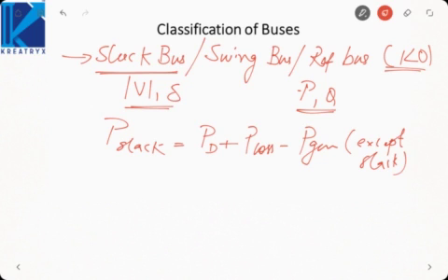Okay. So if it has to supply the net power, then it must have that much reserve power. If it has to have a higher reserve power, then it must have a high capacity. That is why in our power system we will choose the slack bus as the bus having the highest capacity generator. Okay, but practically there is no existence of the slack bus. It is just for the purpose of nodal analysis. One of the nodes is assumed as a reference. Okay, so that is the concept of the slack bus. For any load flow analysis, one bus needs to be considered as slack bus always.